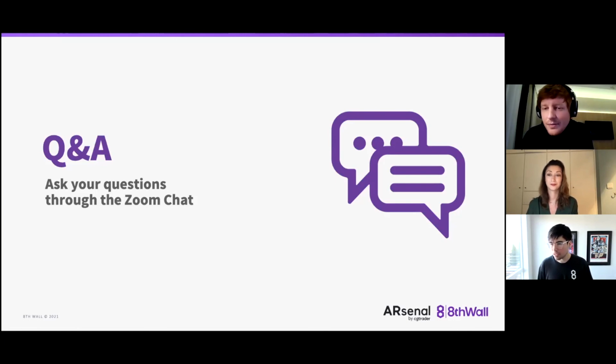No, I mean, when you're designing real-time applications, I have very specific tips for how to make photogrammetry models more performant. And I think performance is definitely something that you want to be thinking about throughout the whole process from beginning to end. So in that case, you'd obviously want to decimate the model that's created tremendously.